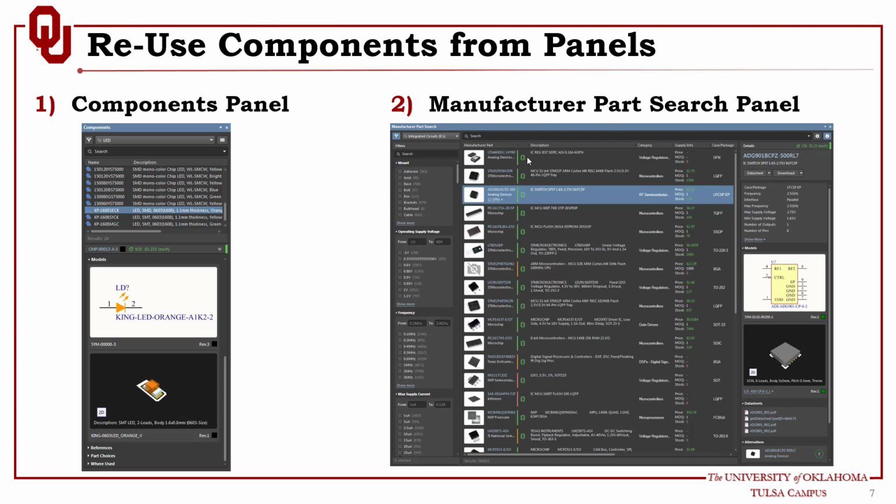Now the components that are flagged with green are in production, and it's highly recommended to use them. You can also see in the corner here, next to the price and the stock available by this supplier, the color coded strip for this component, and if you hover the mouse over this strip, you will get information about the life cycle state.